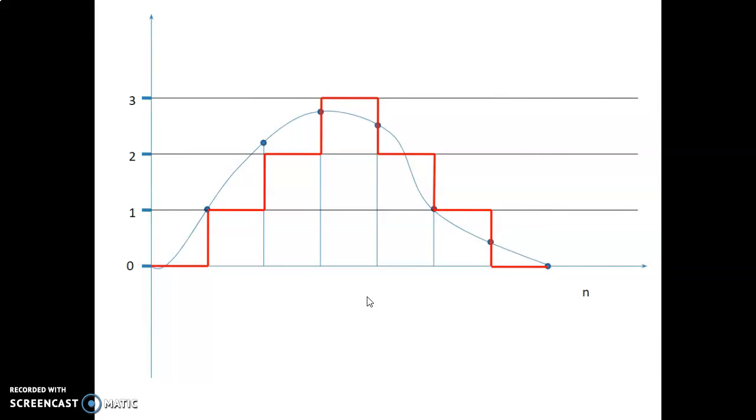So the two steps are now clear: sampling and quantization. Sampling is converting the analog signal, with the help of chopping, into a sampled waveform. Quantization is assigning nearby levels. So the complete waveform we have divided into 4 levels, and whichever sample was at a level we have assigned the same, but whichever sample was not at any level we have assigned the closest level.